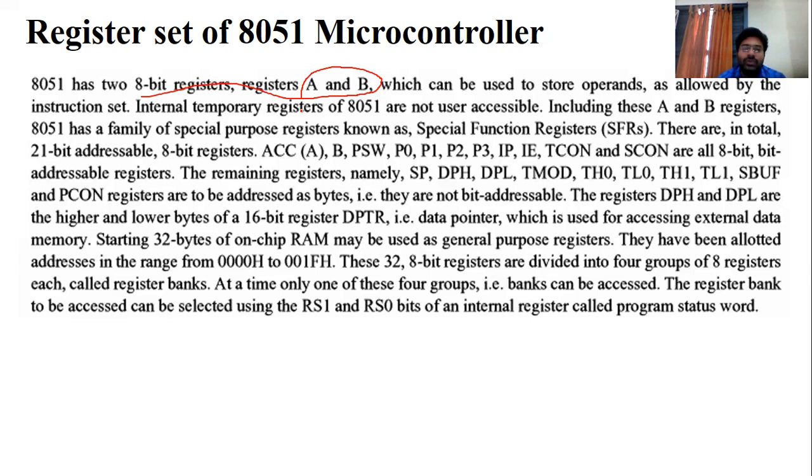Then we have another set of registers: PSW. This PSW is also an 8-bit register. PSW means program status word, and you can also call it a flag register.